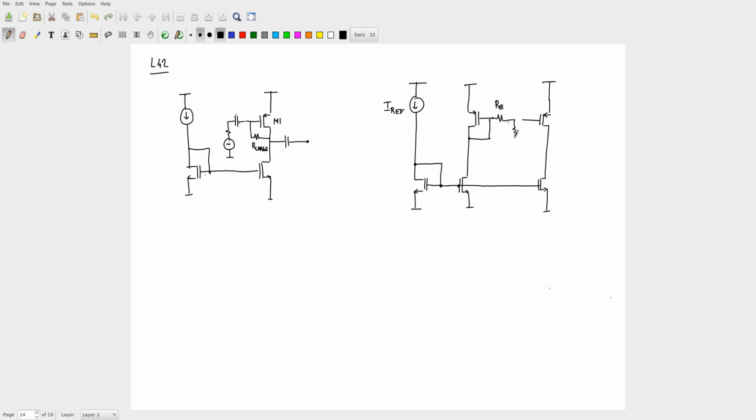You remember? We had this in the quiz also. Yeah, right, because the source has some internal resistance. You want the resistance that the source sees to be much larger than the source resistance. That's why you had this RB. It does not affect your biasing circuit. Okay, and then similarly you can have the output, and this is okay.